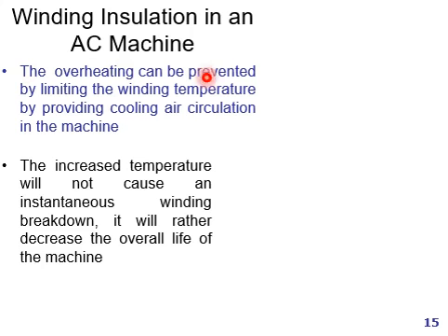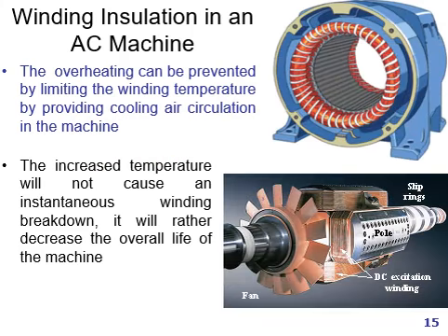The overheating can be prevented by limiting the winding temperature by providing cooling air circulation in the machine. The increased temperature will not cause an instantaneous winding breakdown, it will rather decrease the overall life of the machine.